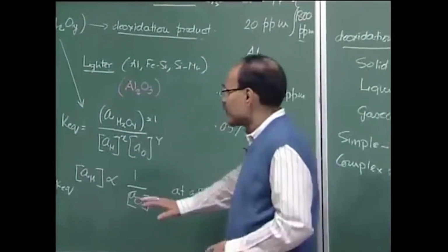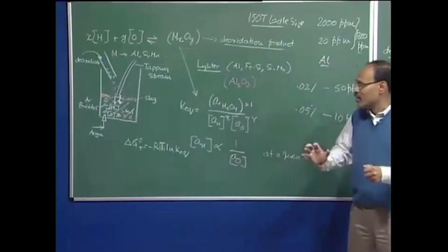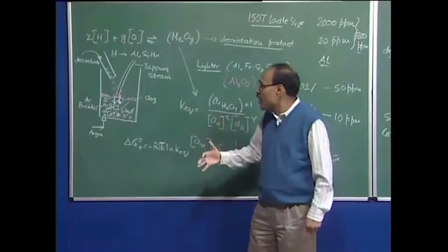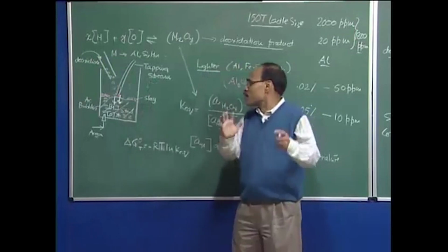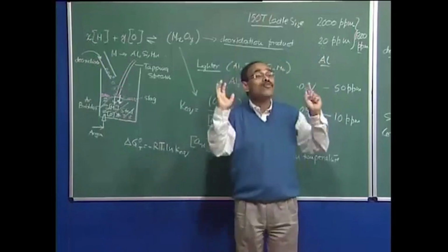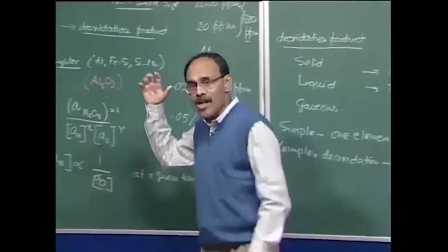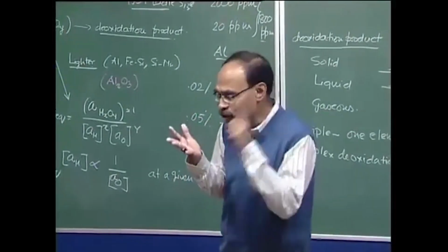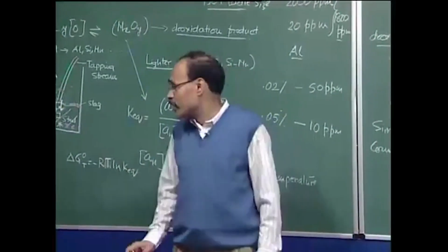It is important for us that the molten steel be free of such deoxidation products. In secondary steel making, or ladle metallurgy, as the processes go on and we generate more and more deoxidation products as a function of time, one of our major thrusts would be, if there are inclusion particles present in the melt, how to drive them out and produce clean steel, which is a very pertinent issue. We do not want dissolved impurities, we do not want much sulfur, we do not want oxygen, nitrogen or hydrogen. At the same time, we do not want unwanted non-metallic inclusions in the steel bath itself.